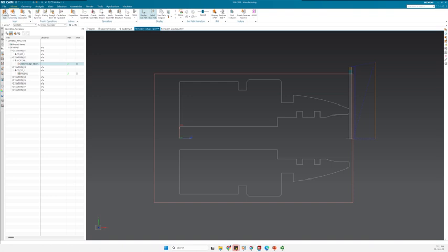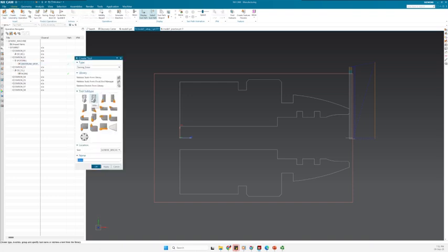So now we'll define, create a tool. I have a drill here. I can have a bunch of other tools. For example, I can have the groove, internal, outside diameter, and so on. But now I will define the drill. You can also retrieve it from library, for example. Then here again, it's better to name the tools correctly. For example, I can say diameter 20 millimeter, and then might be that there would be a different length. So I can just quickly specify here so that it is easier to find it out. Don't forget to define it here.